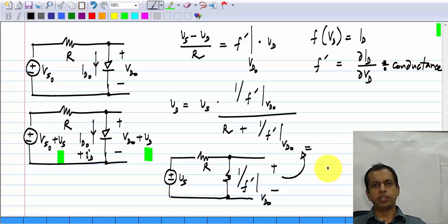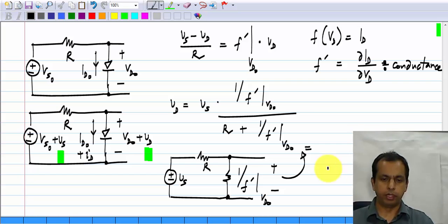So, the reason I showed the equations is to show that it is a general method. Now, what I will show is that every nonlinear element can be replaced by a linear equivalent, and the resulting equations will of course be the same as what you would get if you expanded every nonlinearity in a Taylor series and neglected higher order terms.